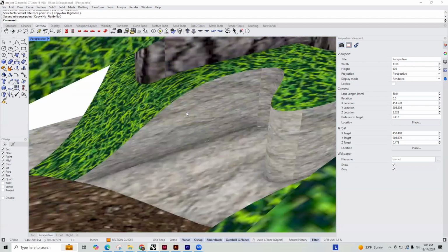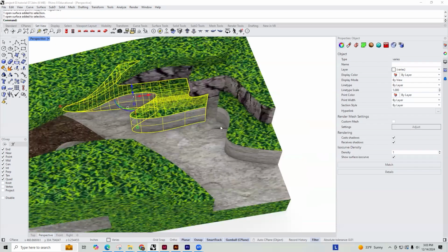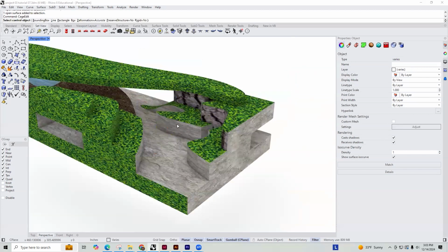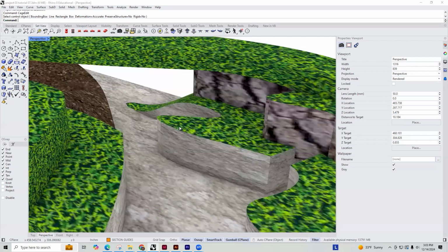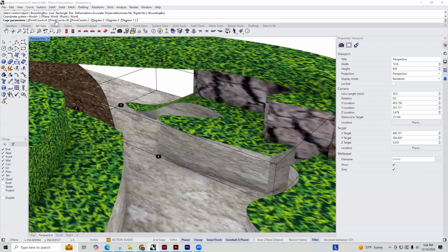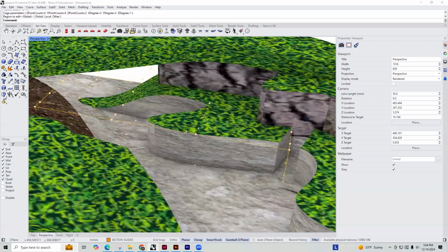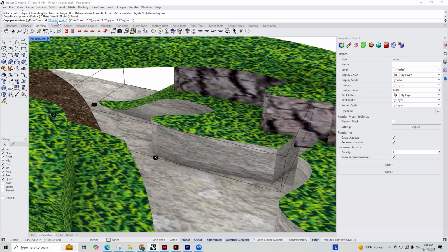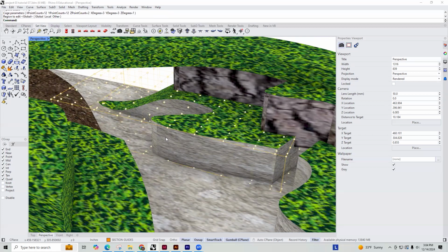All right, so why don't we do that to the rest over here? I'll do that to this plane, cage edit, bounding box, world. Oh, that's why the Y was so crazy. I had it at 28. All right, so cage edit, bounding box, world. Maybe I'll go back to 12 for this because that didn't really give me many options. All right, yeah, that's good.